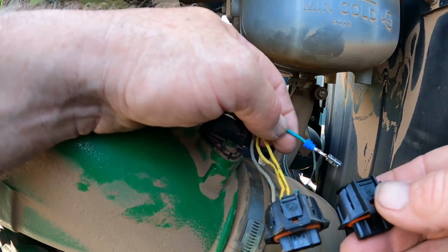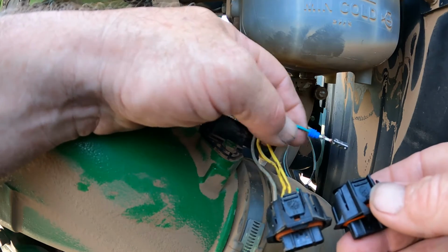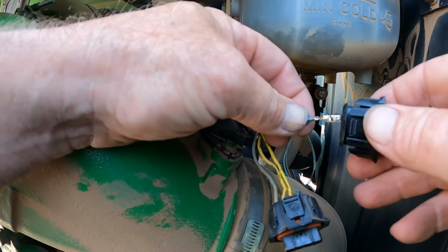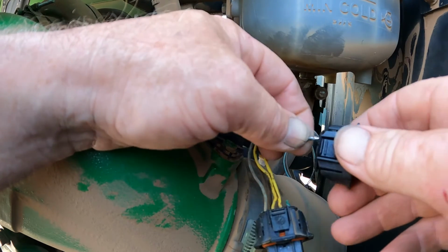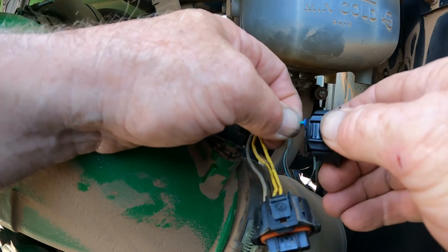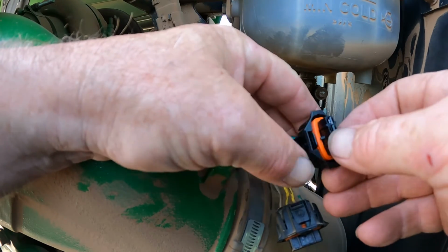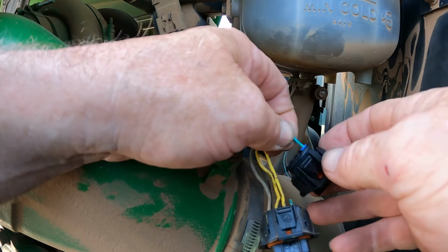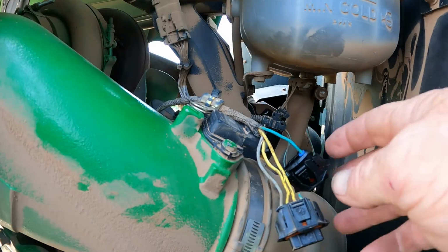So I'm just looking at the connector and facing it exactly the same, okay? And so you're going to slide your terminal up in the back side of your connector as so, and slide it all the way in until it clicks. Once it clicks, it is locked in place, okay? My seal is making a good seal here on the back side, okay?